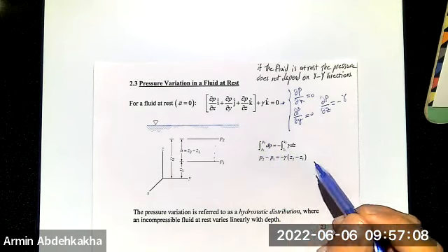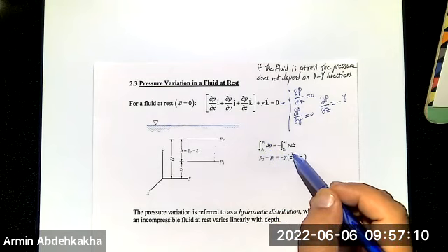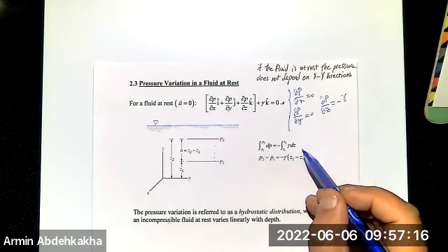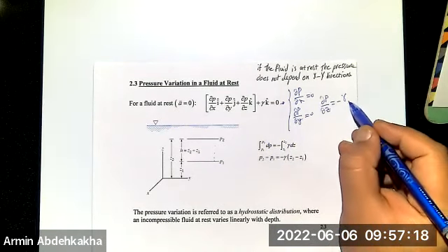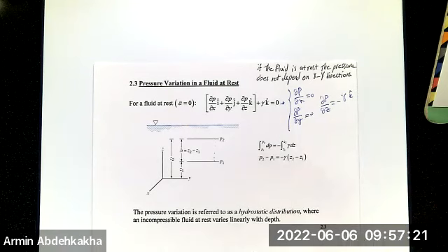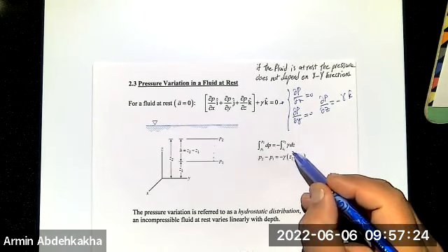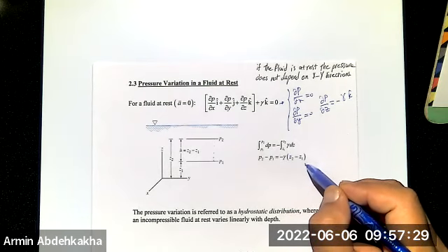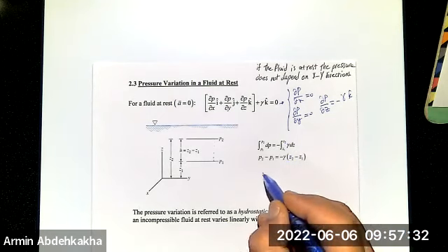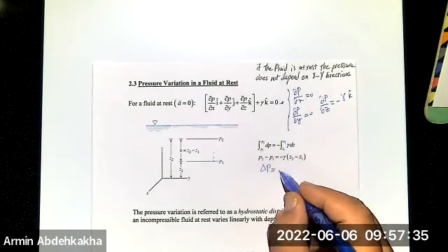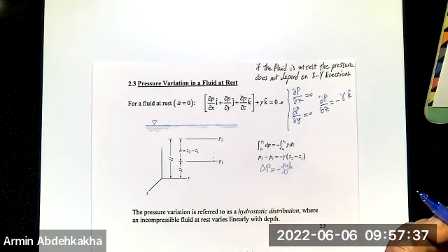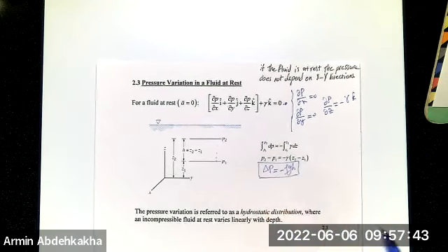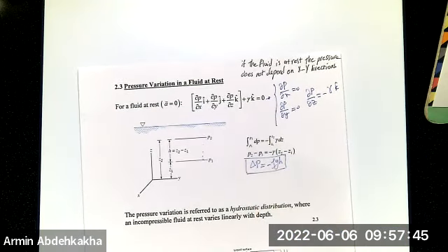The other side we should also integrate, from Z1 to Z2. The only thing that matters is depth, and the only thing that we have here is the K direction, which means dz. Getting the integral of that, gamma times Z2 minus Z1 is the answer. In another form, delta P is rho g h. Okay? That's the only equation that you need when the fluid is at rest.